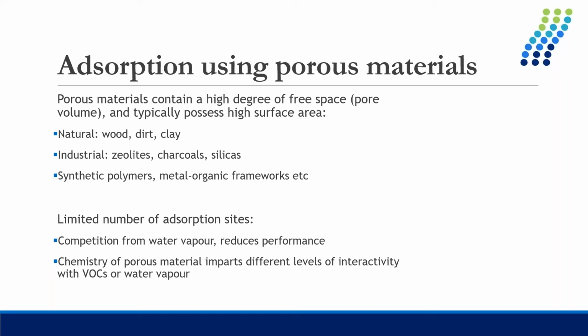In applications in indoor air, for example, you have a significant amount of competition from water vapor. Relative humidity indoors and outdoors will often be at concentrations 4, 5, maybe 6, 7, or 8 orders of magnitude greater than that of VOCs. VOCs are normally present at part per billion and part per million concentration levels. So if we're designing or selecting a material for removing VOCs, we need to make sure they have significant enough selectivity to adsorb the VOCs while not interacting significantly with water. That's what we're going to be investigating today.